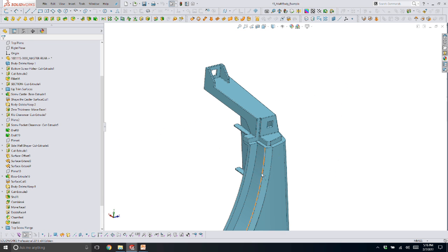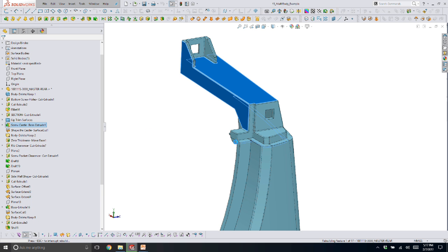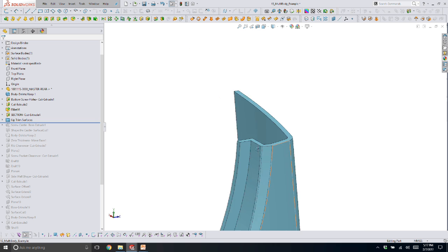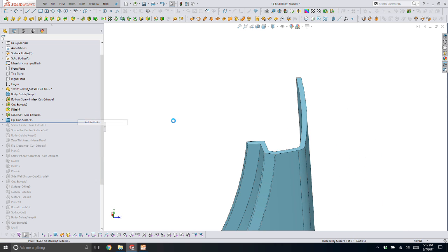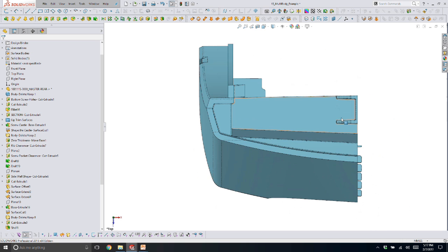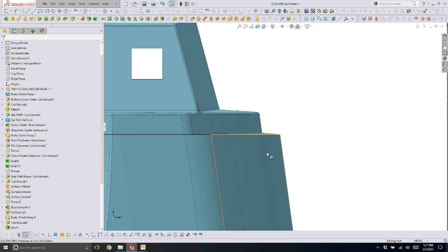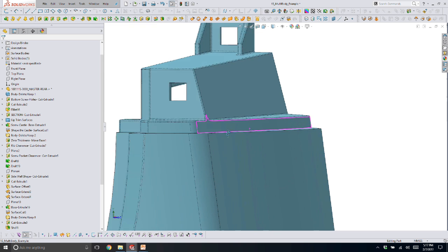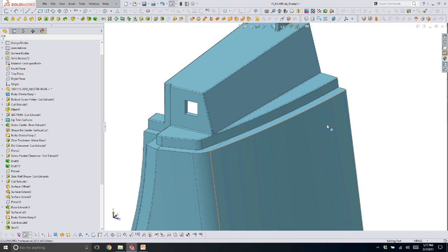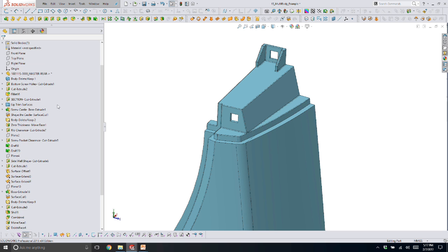Multi-body. Here's a completed detail. I'm going to roll up. And the first thing I needed to do when creating this detail is, actually, let's roll to the end again. If we look at this detail from the side, the other part has to nestle over top of this, and there were some clearance purposes. But if we look at the side, it's actually arcing and it's angling, so I needed to create this face at a corresponding offset to ensure clearance for the corresponding part that's coming in over the top and meeting along this reveal joint.